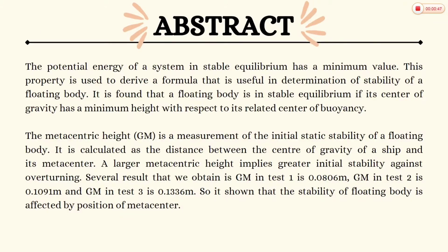So the metacentric height is a measurement of the initial static stability of a floating body. It is calculated as the distance between the center of gravity of a ship and its metacenter. A larger metacentric height implies greater initial stability against overturning.